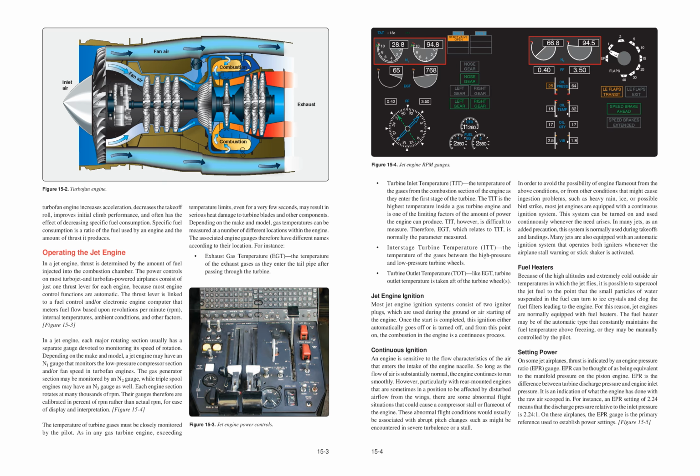For this reason, jet engines are normally equipped with fuel heaters. The fuel heater may be of the automatic type that constantly maintains the fuel temperature above freezing, or it may be manually controlled by the pilot.